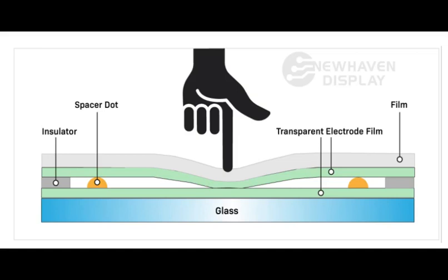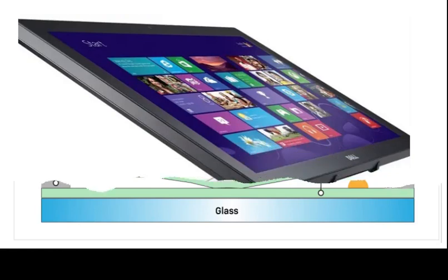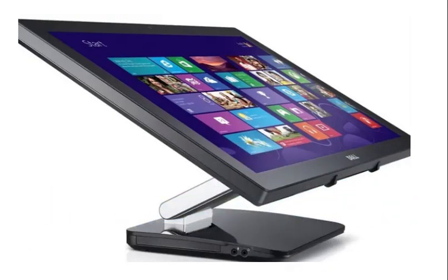SAW monitors can be activated by a finger, gloved hand, or soft-tip stylus. SAW monitors offer easy use and high visibility. Advantages. Excellent image clarity. Even better scratch resistance than surface or projected capacitive. High touch life. Disadvantages. Will not activate with hard items, pen, credit card, or fingernail. Water droplets remaining on the surface of the screen can cause false triggering. Solid contaminants on the screen can create non-touch areas until they are removed.